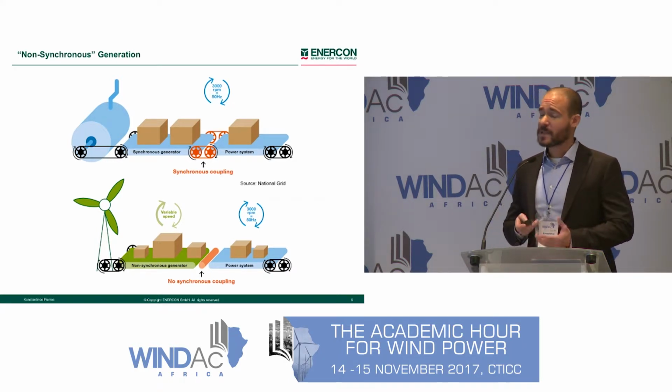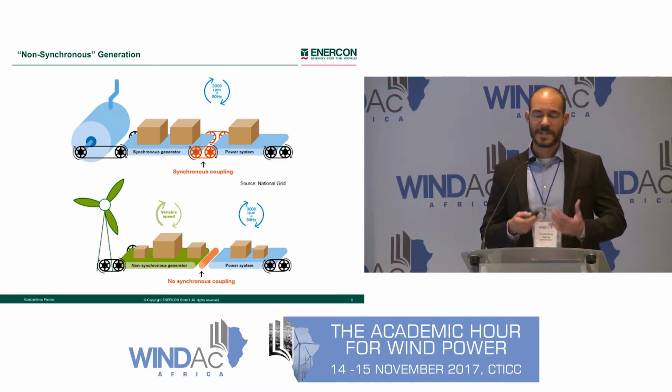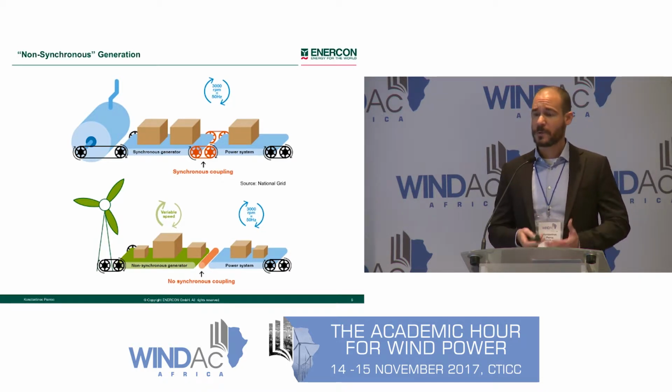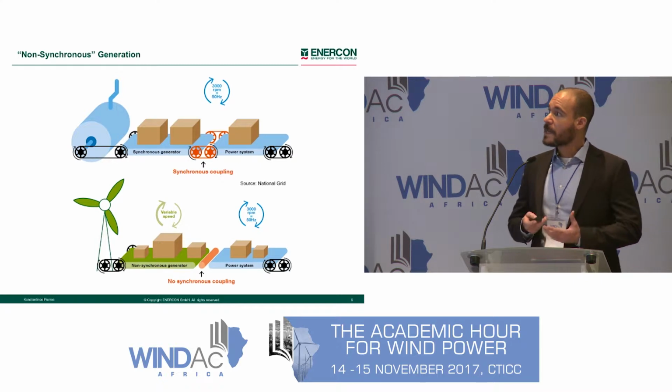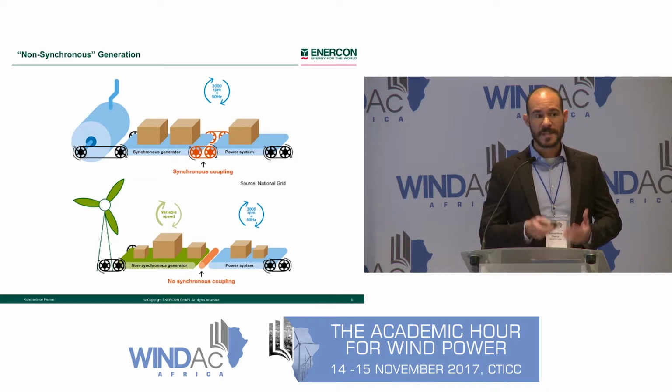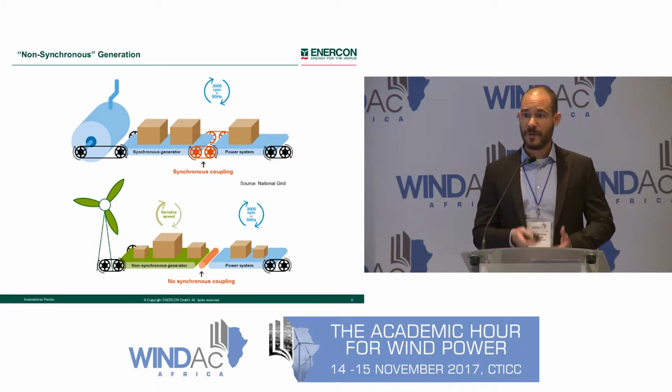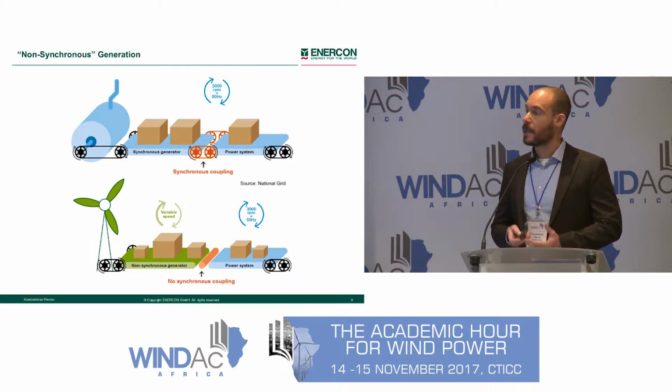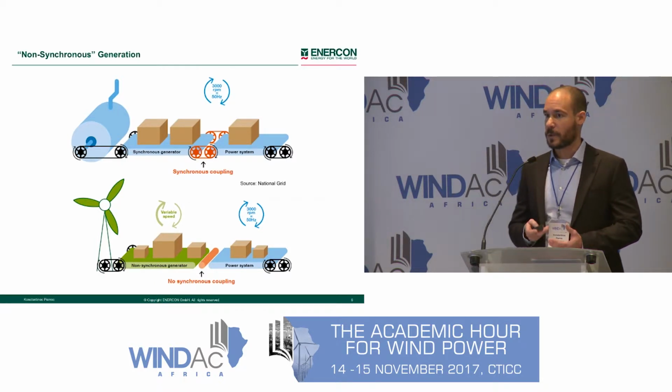As such, displacing conventional, synchronous generating units with non-synchronous ones might lead to frequency control challenges, with steeper rate of change of frequency events and lower frequency nadirs occurring.